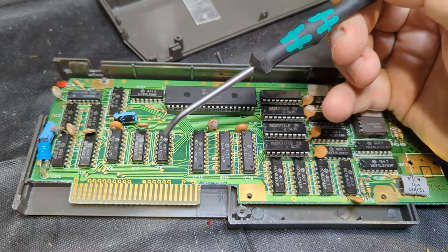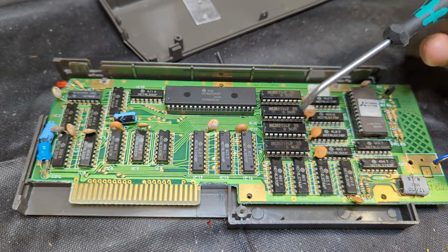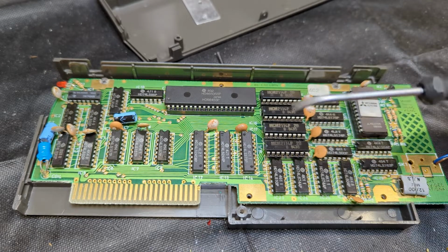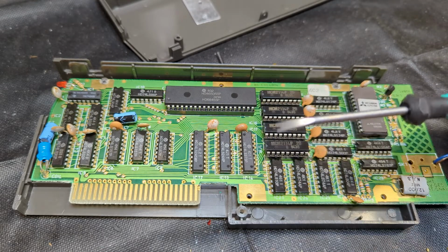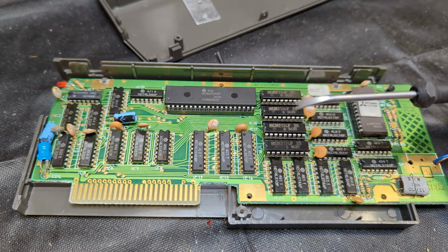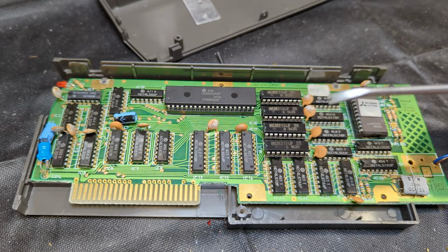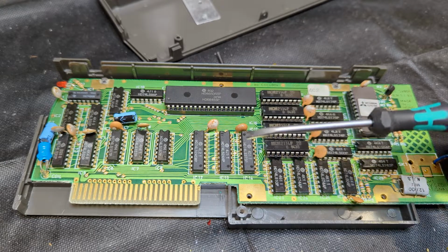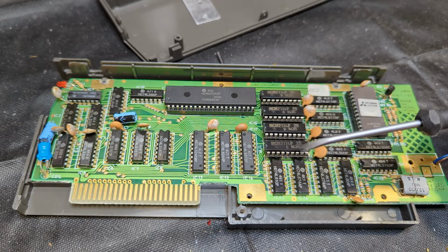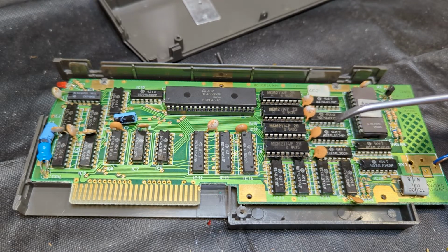Over here are our multiplexers that multiplex the access to the video memory between the CPU and the CRTC, because they both need access. The main processor needs access to update what's going to be displayed on the screen, and the CRTC needs access to actually display it. And yeah, there's various other bits of glue logic that latch things and control access and decode signals and so on. So we'll have a quick look at that in the schematic in just a moment.